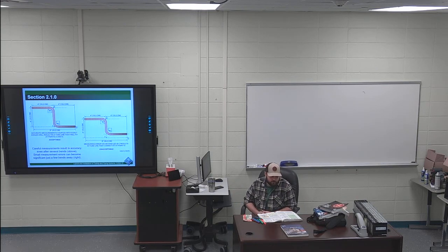In 211, tube gain. Second paragraph is an online test question. A good rule of thumb for most standard tubing materials and radius blocks is that the tubing will gain approximately 1 tube diameter for every 90 degrees of bend. There are also tube gain charts that you can see on page 23 to determine actual gains. Last paragraph on page 22, first sentence is highlighted. The precise amount of gain is related to the diameter of the radius that is used. Table 2 provides that. But yes, you have to determine your gain before bending your tubing.